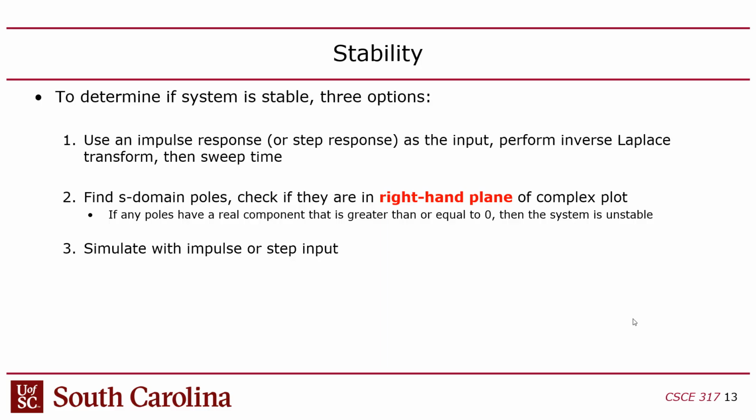Well, you use trial and error. Well, no. What you do is you do an impulse response. It turns out there's this thing called an impulse, where you give it an input of 1 for an infinitely small amount of time. That's called an impulse, and it includes all frequencies. If you do the Fourier transform of that, it has all frequencies in it. The same thing happens if you give it a step. So if you go from 0 to 1 and just keep it at 1, a square wave, right? Square waves also have an infinite number of frequency components.